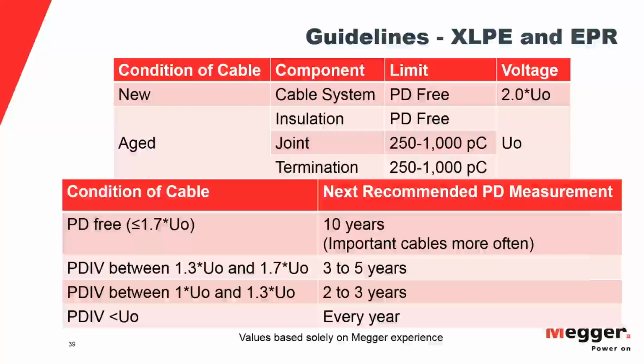The other problem with square waves and eventually triangular waves is you tend to have overshoot at the voltages. So your RMS voltage might be, pick a number, 10 kV, but your actual peak voltage could be considerably higher than that because of the overshoot, because of that fast transition time.